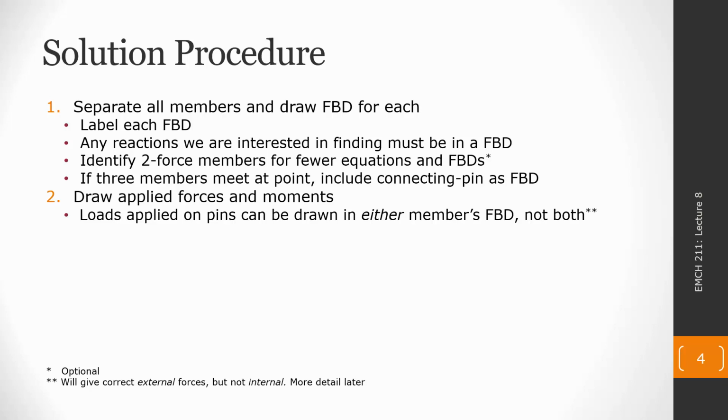However, if a force is acting on one member but not a second member, in the free body diagram for the second member, it's not going to know directly that that force is acting on the first member. Now, everything's going to be linked together by internal forces, as we'll see, but we're only copying exactly the forces that act only on each individual member in their free body diagram.